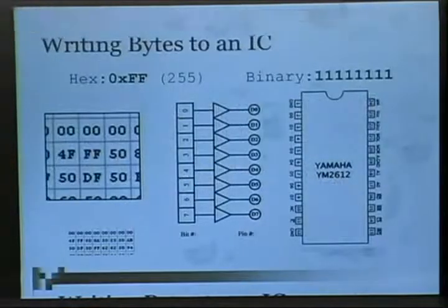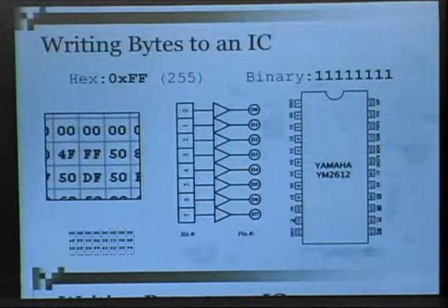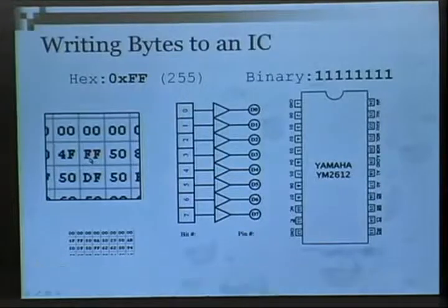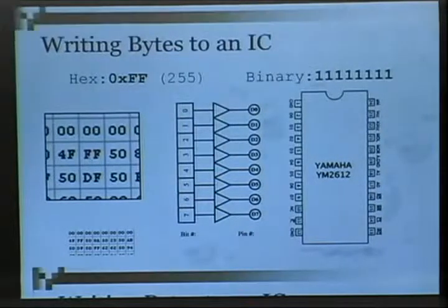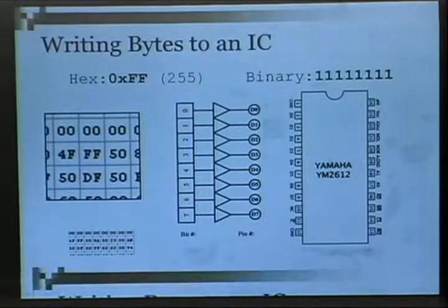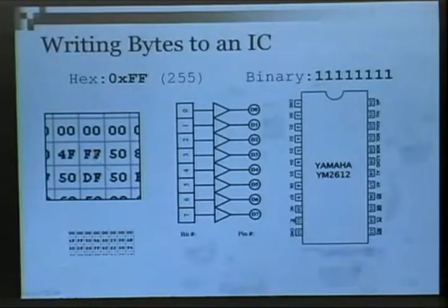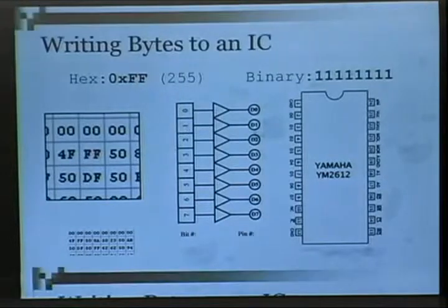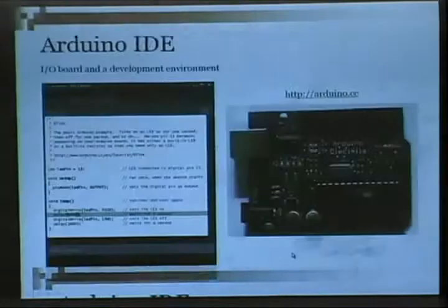How do I get data into it? Well, the first thing I needed to know is hex to binary conversion. The image you see on the left in red, that's the VGM file data. That's the instructions in that file that has all the music, register changes you need to do, set the channel on or off. And these pins, you remember that pinout has D0 through D7. So just take those hex values, convert them into binary, and just map them to the correct pins. Just dump them like a player piano.